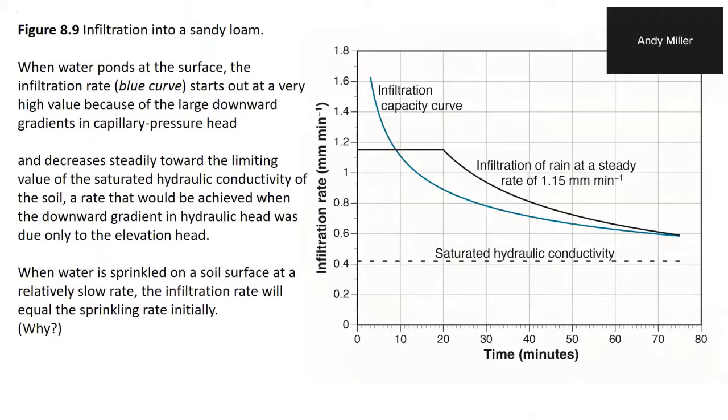Now, we are going to use the Green-Ampt method to try to simulate these patterns. But I'll just point out that there are two different representations of the Green-Ampt method between the Hornberger book and the Dingman book. It's not because Hornberger doesn't know what he's talking about. He's written some of the seminal papers about it. But the point is that they chose not to go there. So they only talk about a case that looks like this. In other words, the cases we're going to work with in the first spreadsheet essentially assume that the rain rate is always greater than the infiltration capacity, and so you can watch the infiltration capacity come down. You're not dealing with this case until we get the version of the spreadsheet that comes with the Dingman text.